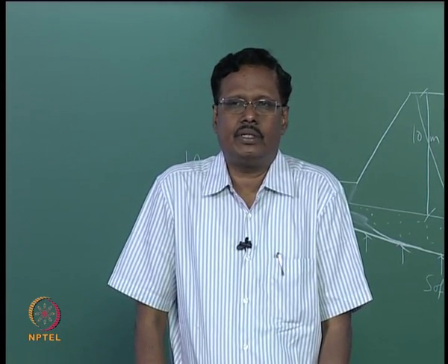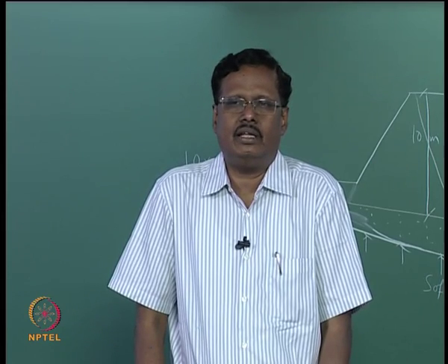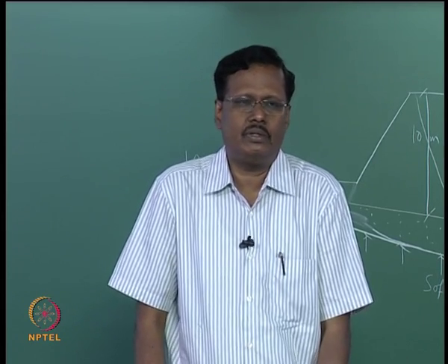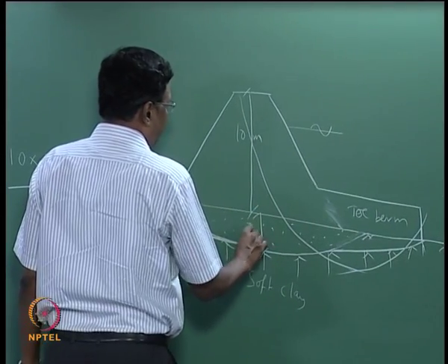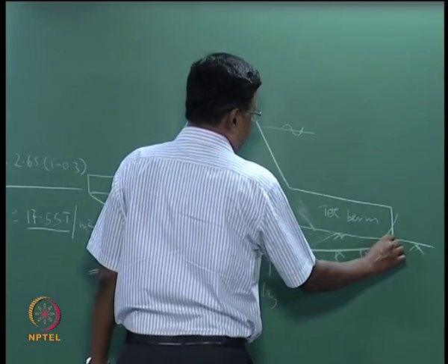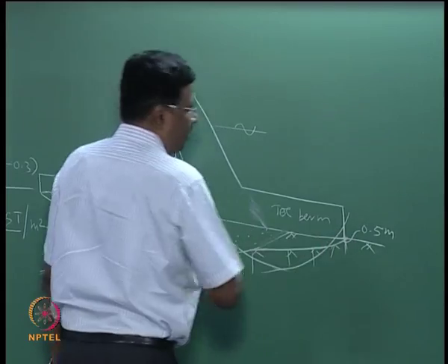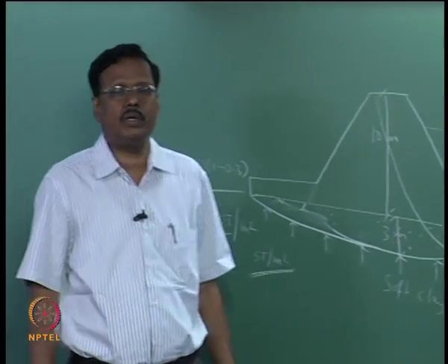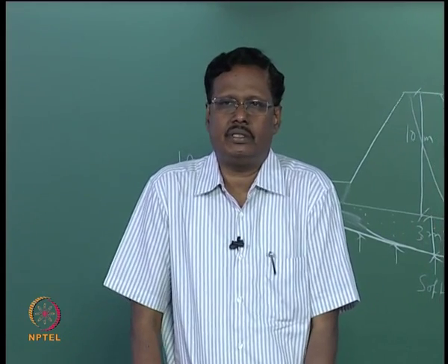The area is increased to take the foundation, this is what we have to do. But in some of the cases, we do not treat the soil if it becomes very expensive. We calculate the settlement may be about 3 meters here, about 0.5 meter here, so the differential settlement is about 2.5 meters, total settlement about 3 meters.